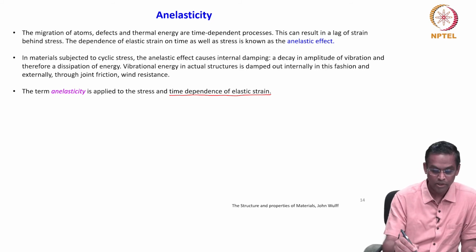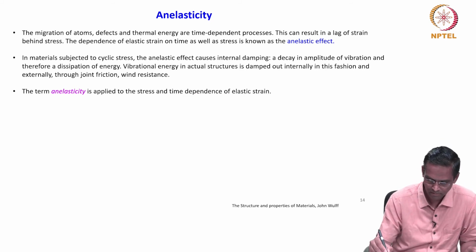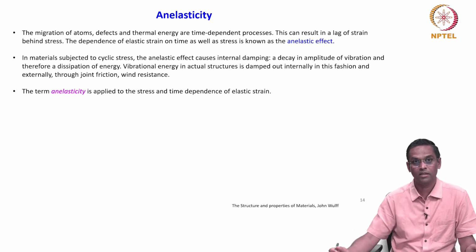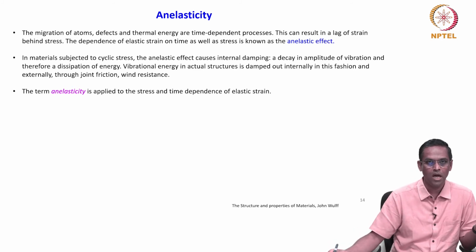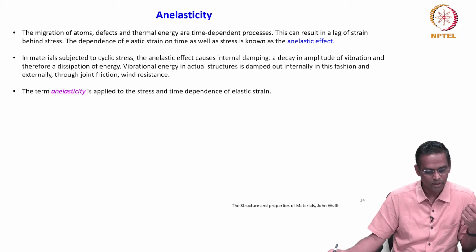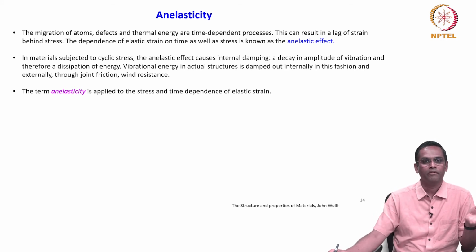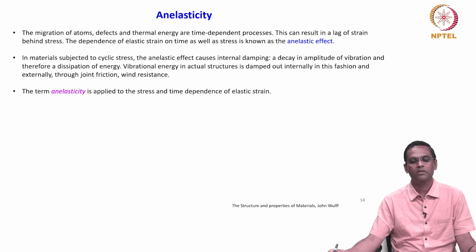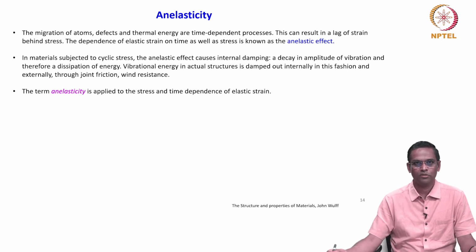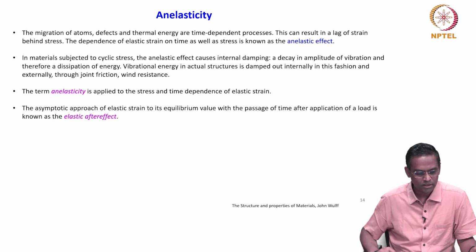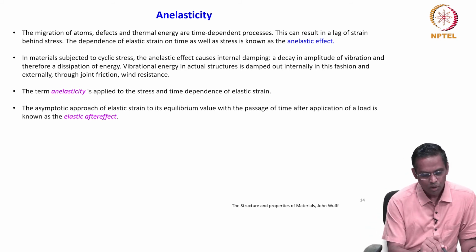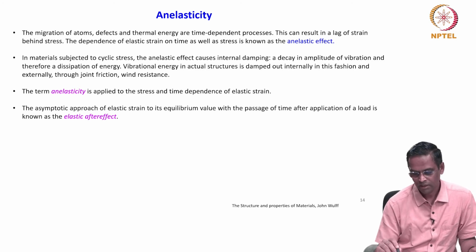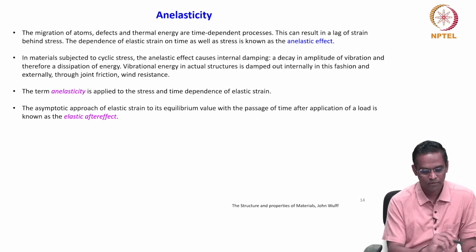We will be using this terminology later in plastic deformation also, when we discuss high temperature deformation behavior called creep and so on, right. So, this is a fundamental starting point. The asymptotic approach of elastic strain to its equilibrium value with the passage of time after application of load is known as elastic after effect.